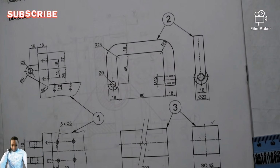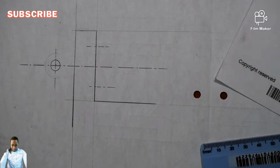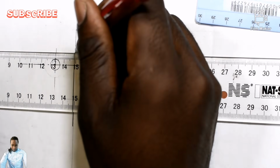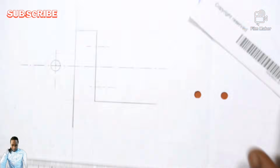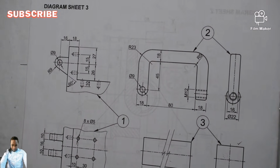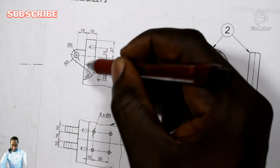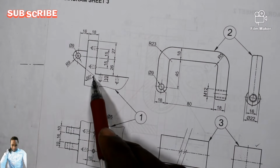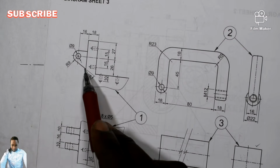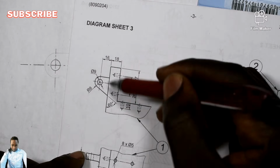Then once it touches there, I can go straight horizontally, and I'll draw it faint, because I don't know how part 2 is going to be fitted in item 1. You understand? Okay, then the set is angle 60 degrees. This one is supposed to be at an angle of 60 degrees, and your reference line is supposed to be a horizontal component.